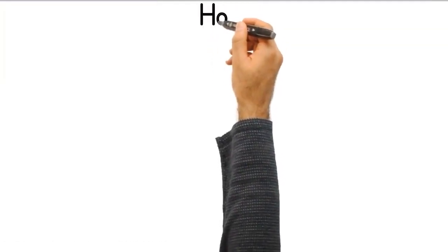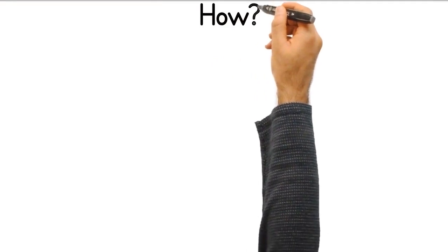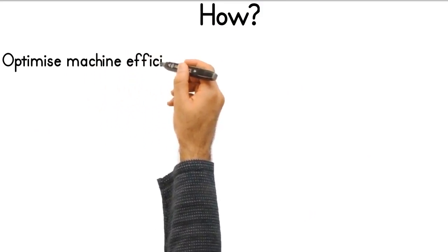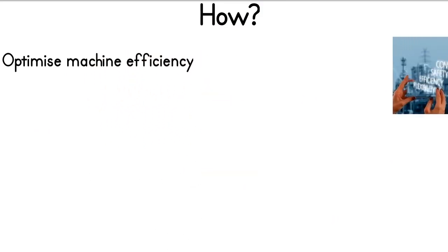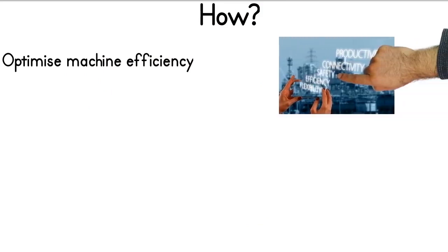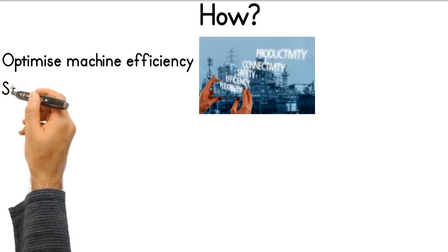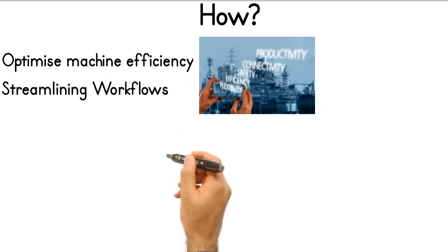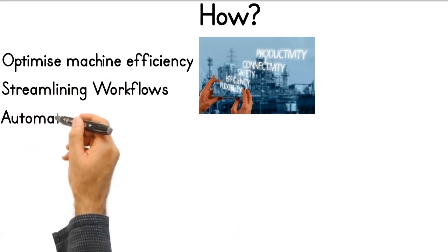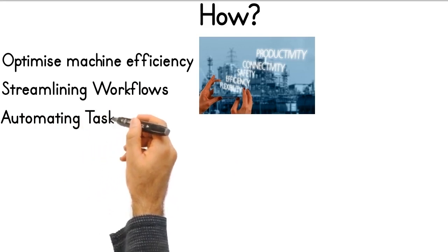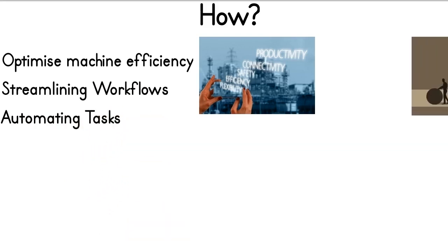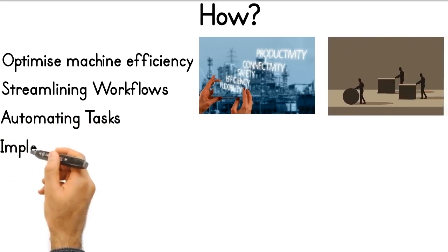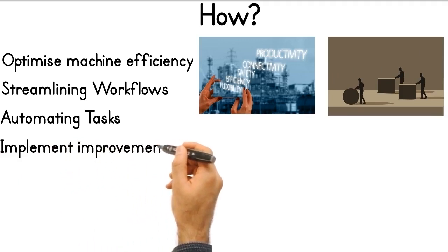How is man-machine cycle time reduced? Regular preventive maintenance, calibration, and machine upgrades help improve the speed and performance of the machines, reducing idle time, and ensuring machines are working at optimal levels. By eliminating unnecessary waiting time for operators or minimizing manual handling tasks. Reviewing and re-engineering workflows to ensure smooth transitions between machine tasks and operator actions. Introducing automation to handle repetitive tasks or assist in the machine setup and operation process.